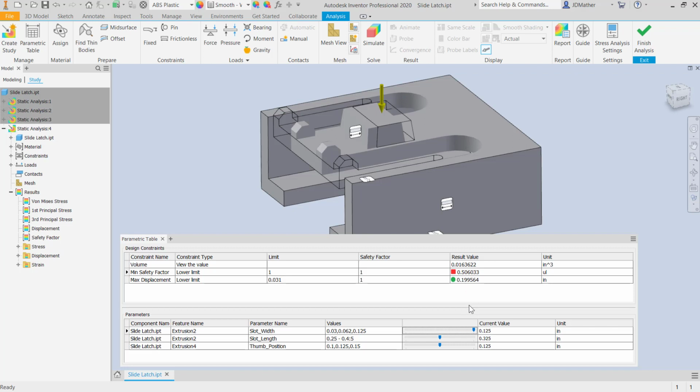But everything that I see is, in most of the positions, our displacement is much greater than needed, and so I think the obvious first attempt at achieving a solution might be to reduce the load. So I'll reduce the load pushing down on this and run the analysis again and see what we get.